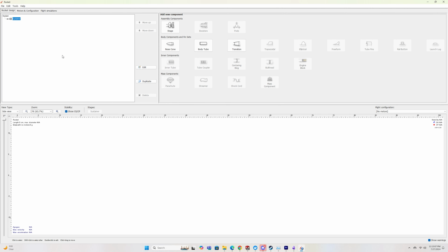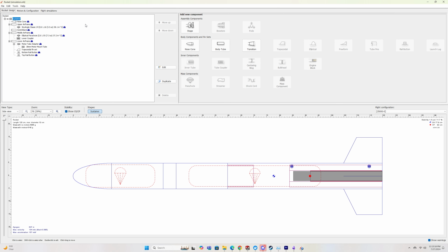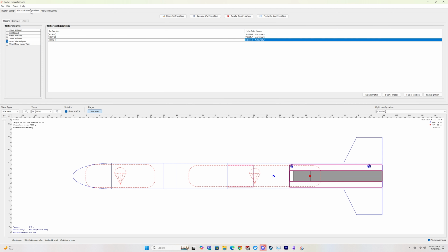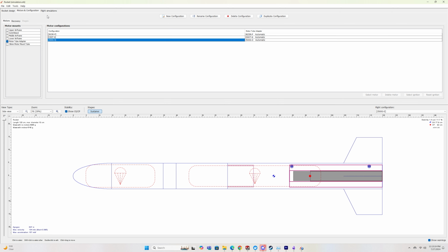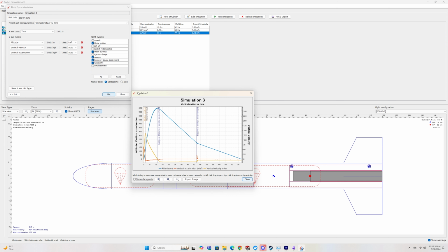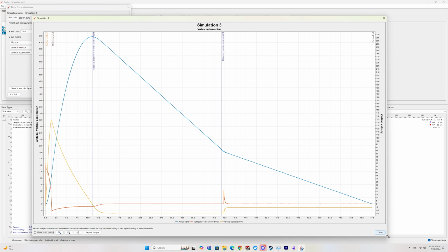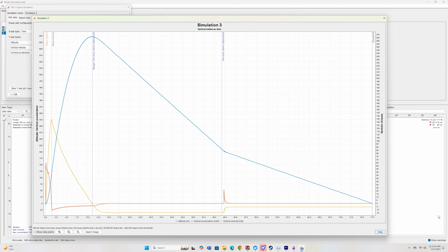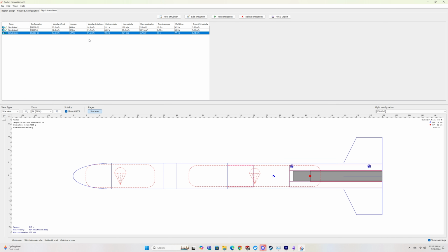We then outline the design of the rocket using a simulation software such as OpenRocket, so that we can design while keeping in mind things such as stability and center of gravity. It also provides configurations for different motors and plots out the expected path of our launch. For this, we'll be using a dual deployment system consisting of a drogue parachute to reduce the shock from the deployment of our main chute. Now, let's go and build this rocket.